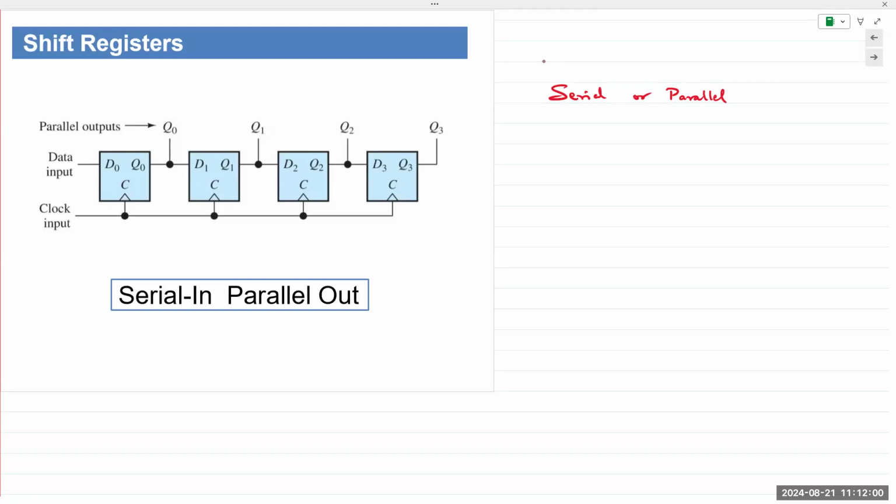Okay, so USB is a universal serial bus. It's the successor to the serial port. The serial port itself, if I remember correctly, has 9 pins. A parallel port had about 25 to 30 pins. Parallel ports were used to send information to printers. Serial ports were used to interface many of the instruments that you see on the lab benches. Nowadays, of course, it's just USB. But if you look at any older instruments, they will have a serial port in the back. And that's how we used to connect instruments via the serial interface.